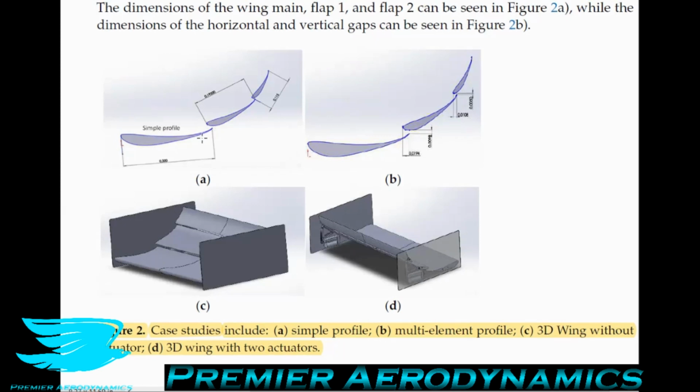So as I mentioned, the distance between the trailing edge of one airfoil and the leading edge of the next one is actually negative 5.2% of the chord of the upstream airfoil. So there's actually quite a lot of overlap here. And then the distance between the one airfoil vertically and the other airfoil is 3.8%.